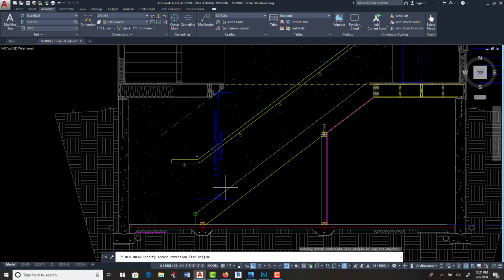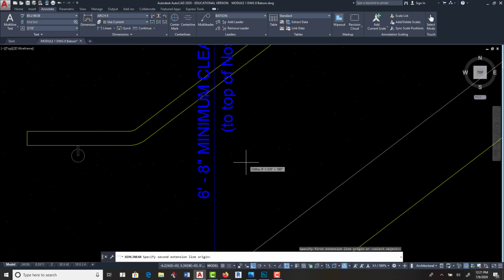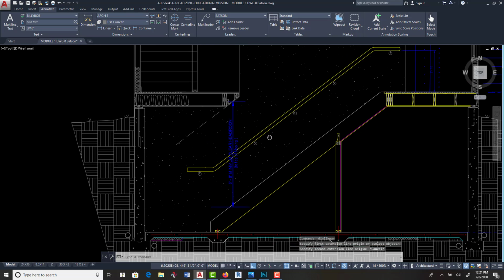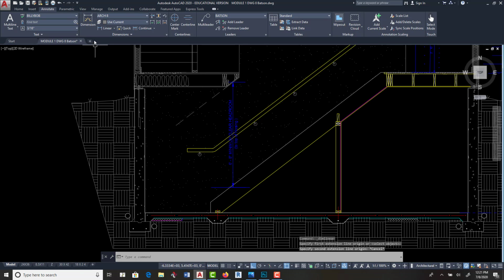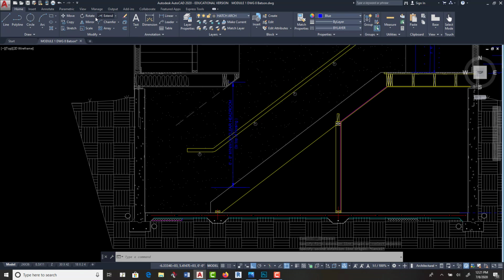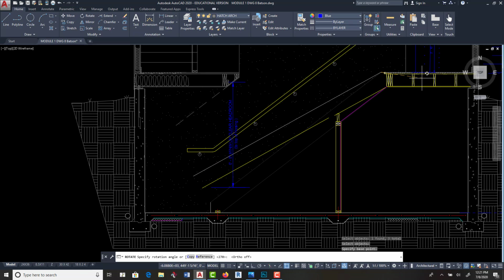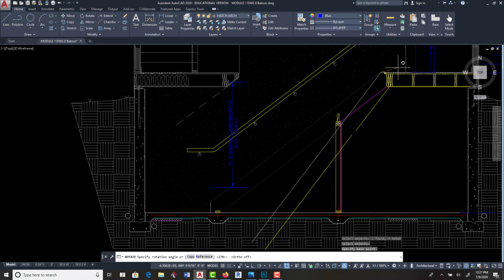So you know you've got to clear this space, by the time you get to here on the stair, this space has to be a minimum of 6 foot 8 inch headroom. So the longer your treads, your stringer is going to do what? It's going to be longer. But the shorter your tread, the steeper your stairway is.